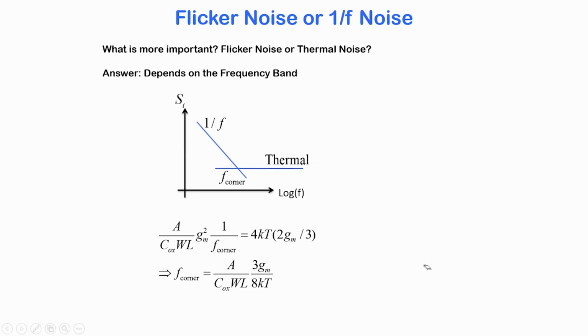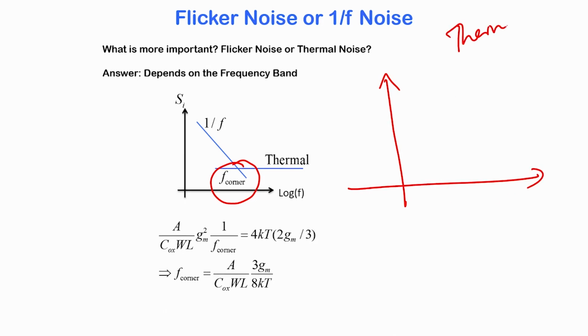And finally, the very last topic has to do with something called the corner frequency with regard to noise in a MOSFET. And what is corner frequency? We know that in a MOSFET there are two key components of noise: the thermal noise and the flicker noise. Thermal noise is rather frequency independent, it is almost constant at all frequencies, and therefore it is called white because it has all frequencies in it. But flicker noise has a 1 over f dependence.